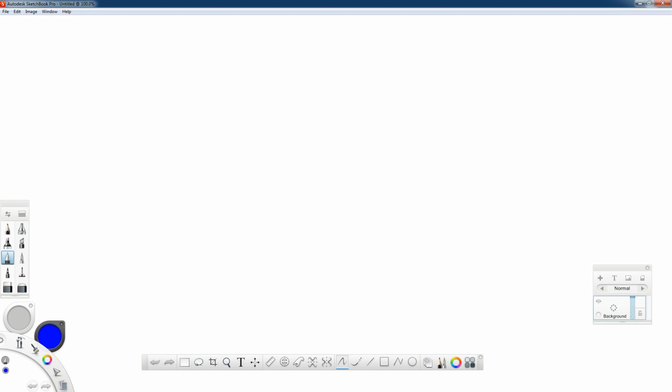So from this we can write down our stress tensor. We have 0 stresses in these positions. We have a non-zero tau xz and a non-zero tau yz. Being symmetric, we have these stresses in these positions as well, and we have a 0 sigma z down the axis of the bar.